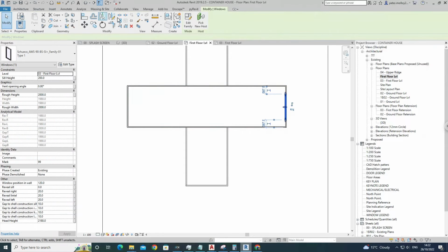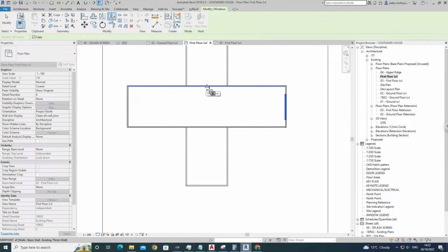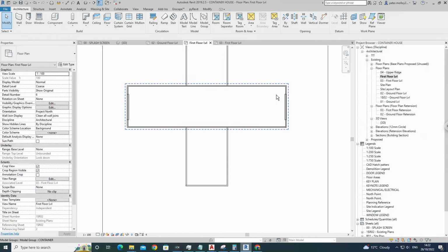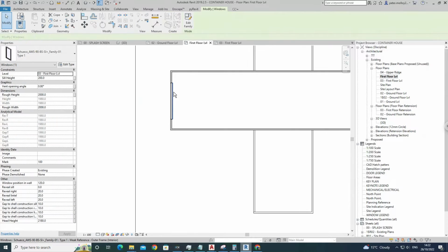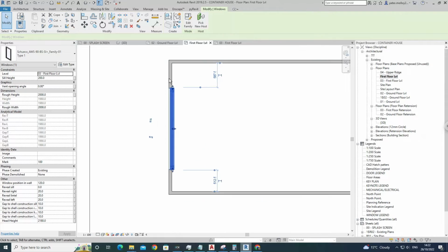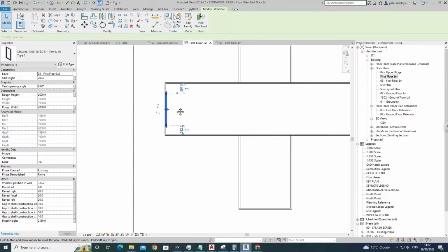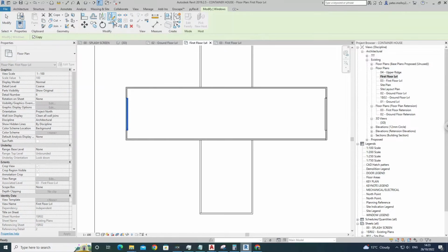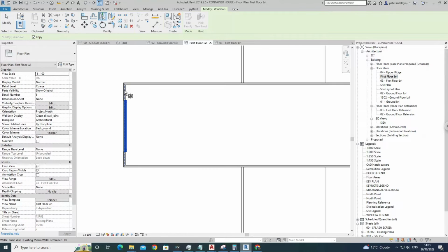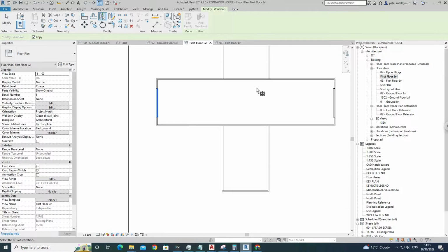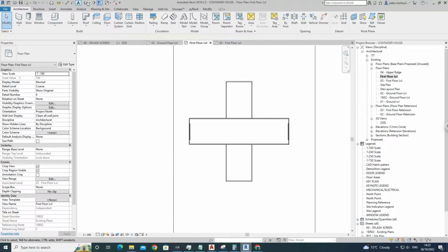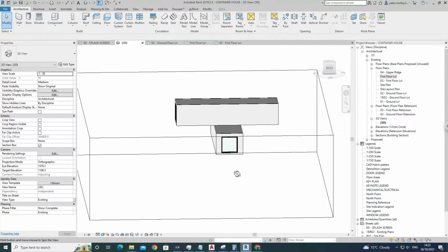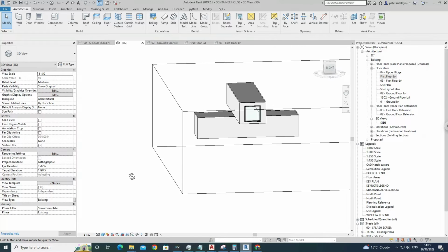And I'm going to duplicate this guy. I'm just going to grab the center, the midpoint of this. And what that'll do is it essentially grabs the window and it flips it over to the far side. And once it sits in the same plane as the wall, we'll grab it and it'll sit in nicely. So that's this tool. You can also use this tool as well, but that's more for if you're aligning with walls and such. But this one's real handy for just grabbing a midpoint and flicking a window over. As you'll see there. Yeah, it's coming in real nice.